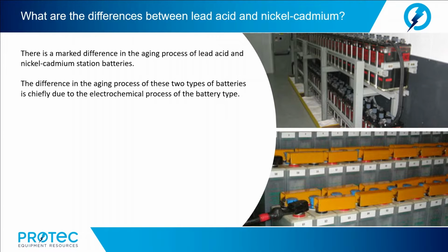In contrast, the primary failure of nickel-cadmium batteries is due to the gradual linear aging of the active materials in the plates. The electrolyte of the nickel-cadmium battery only facilitates the chemical reaction. It functions only to transfer ions between the positive and negative plates, but is not chemically altered during the process like the electrolyte of a lead-acid battery.